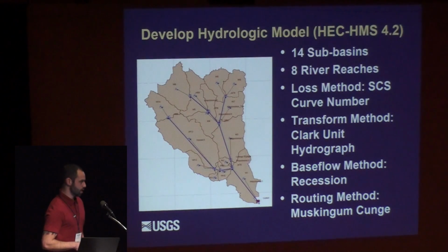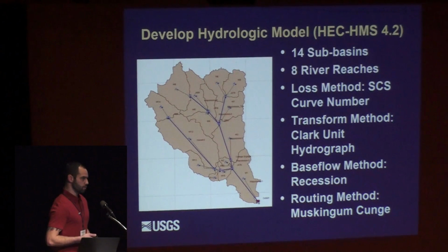So the data that these gauges collect, I need to build a hydraulic model. I need the precipitation gauges in a different way than normal. You might think about a rain event, normally, with the total precipitation, say you got 5 inches of rain. Well, I need to know how much rain you got in time steps. So our gauges will tell you in 15-minute time steps how much rainfall you're receiving, so you know how much to apply over your watershed throughout time.